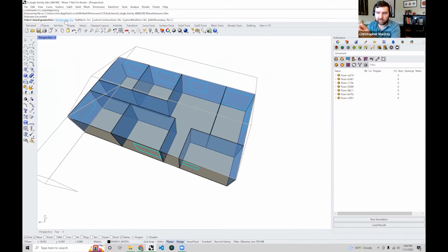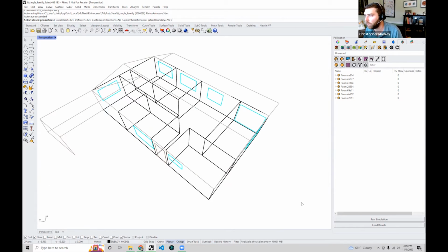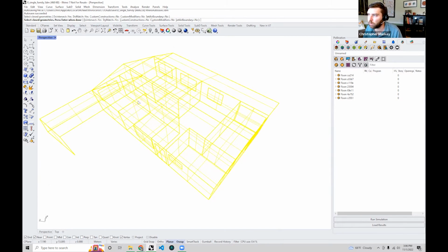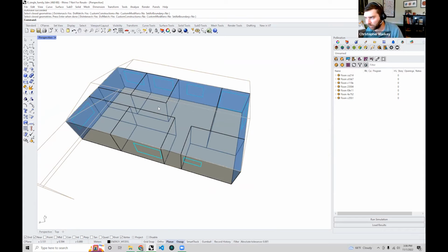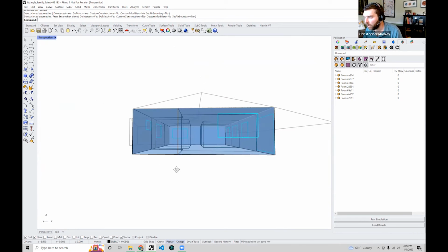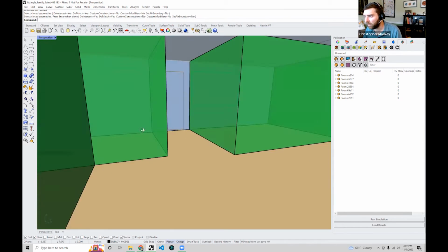As you see, that was one of the golden rules of Honeybee geometry and of Pollination model geometry. So the command will take care of this automatically for you in the intersection calculation. And then it does a matching, which is basically the assignment of the indoor boundary conditions. You could also set custom constructions on this, but I think all the defaults are good for our case here. So I'm just going to select all the rooms of the model and hit enter. The command is smart enough that it should only operate on the rooms, even though I selected a bunch of other geometries there.